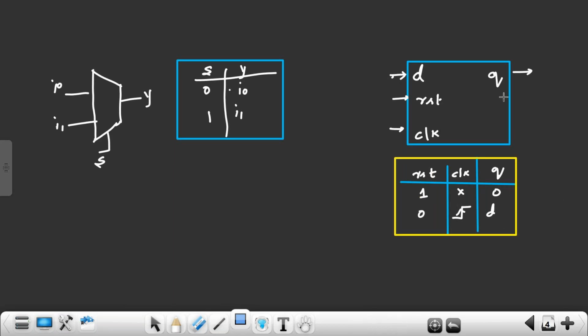But now, how can you tell what is present inside a D flip flop? By using gates. You have read latches, right? After latch, you are going to create the flip flop. Verilog or VHDL lets you easily capture the behavior without worrying about what is present inside. That is done by the synthesis tool. You need not worry. You can directly write the Verilog program. I can easily write a Verilog program for a mux. How to write it?